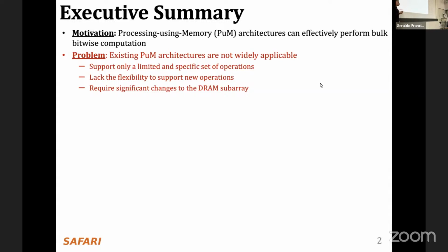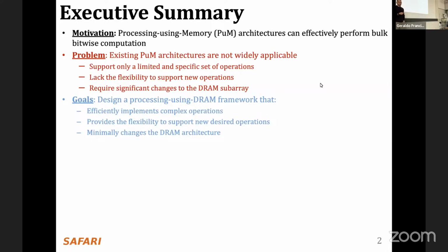So the goal of this work is to mitigate those three problems and design a processing-using-DRAM framework that can, first, extend the implementation to other operations like addition or multiplication; second, provide a flexible way for the user to implement arbitrary operations as needed inside DRAM using the available processing-using-DRAM primitives; and third, minimally change the subarray organization or design.